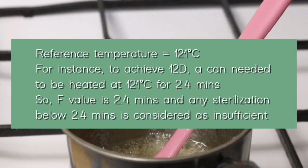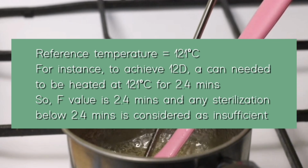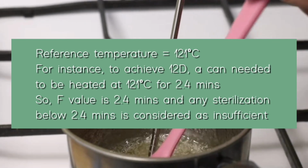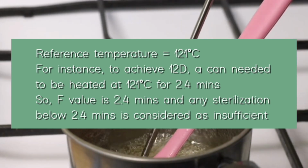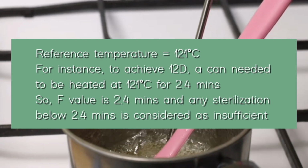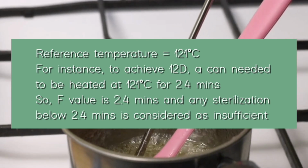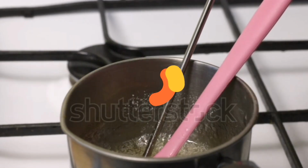For instance, to achieve 12D, a can needs to be heated at 121 degrees Celsius for 2 minutes and 4 seconds. Thus, the value of F is 2 minutes and 4 seconds, and any sterilization of less than that is considered inadequate. That is all from us for now.